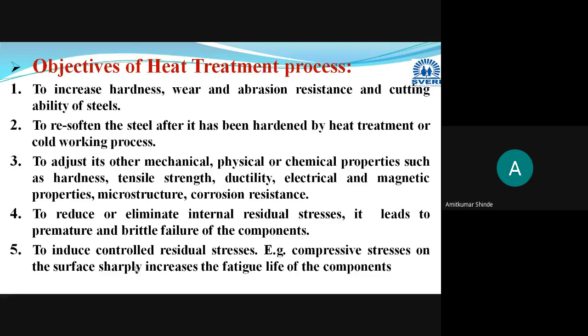As long as the stresses present are controlled and compressive in nature, they will increase the fatigue life. So you can use the heat treatment process either to eliminate the internal residual stresses or to induce controlled residual stresses to improve the fatigue life of that component. These are the objectives of the heat treatment process.